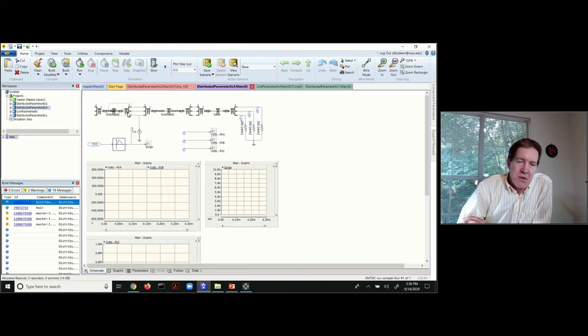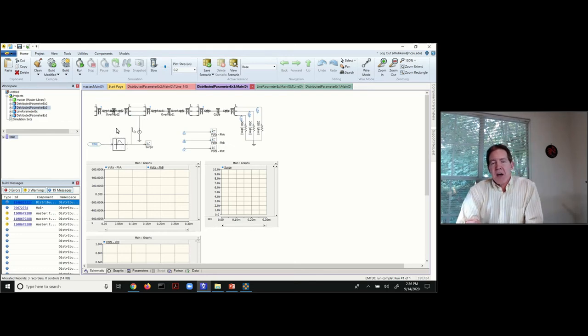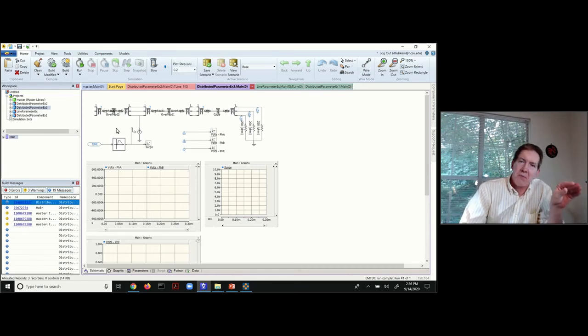It's made to be put at the end of transmission lines, and it splits this into the individual phases so you can access each phase. With this overhead line model, one way of doing it would be to draw it as a three-phase element where the connection is three-phase by default. But suppose you want to put a fault or a current injection on a single phase.